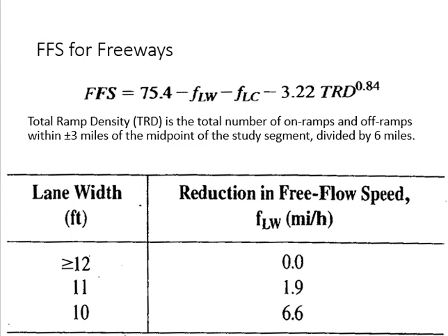Okay? So according to them, this emergency lane is part of lateral clearance. It's not part of the road. So if you have the yellow line, the lateral clearance starts. The 5 or 6 or 10 feet of the emergency lane is part of lateral clearance. So it will be from the yellow line to the sidewalk. Clear?